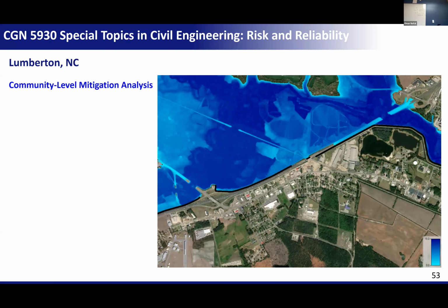All these got full protection. However, the water is still backed up behind the levee and overflows some buildings, around 50 buildings. But it's better that you deal with 50 buildings rather than dealing with 1,900 buildings. You can buy them out, or you can provide them money so that they can increase their elevations.